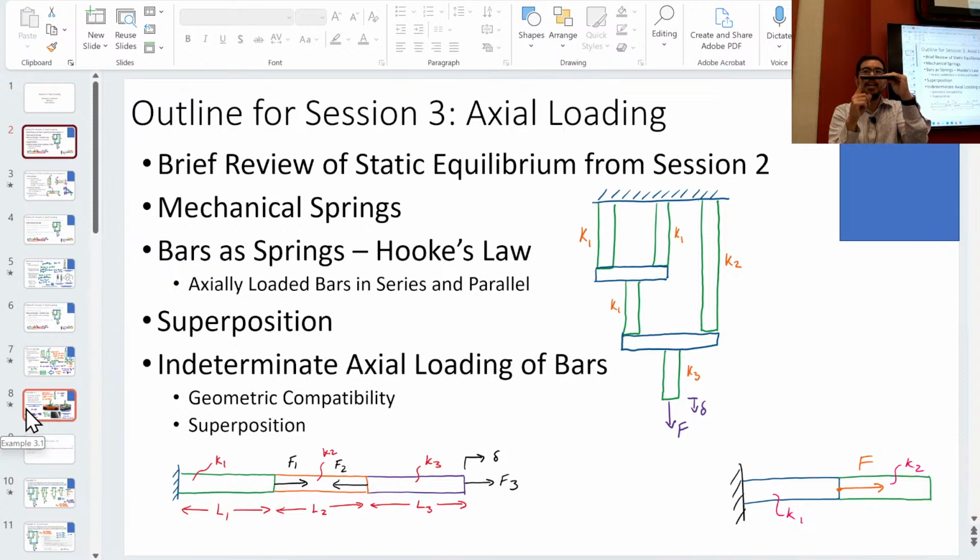Nothing's moving, but I can crank up the forces. I can crank up this force, I can crank up this force, I can crank that moment. I can crank up the loads. But everything's static. So how can I calculate things? I'm at a loss. So again, we need to know something about the deflection of the object. We need to know something about the squishiness of the beam, in order to be able to solve for the forces and displacements.